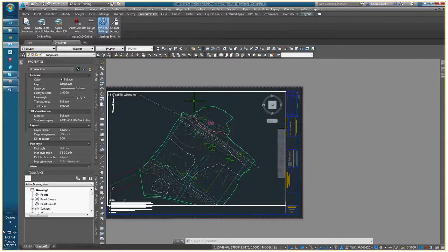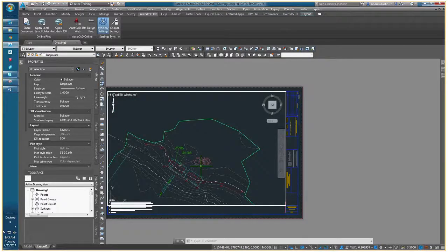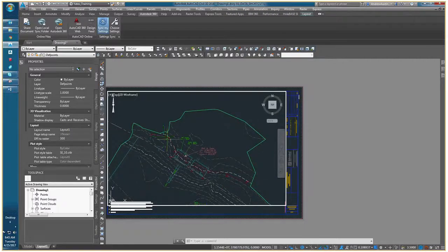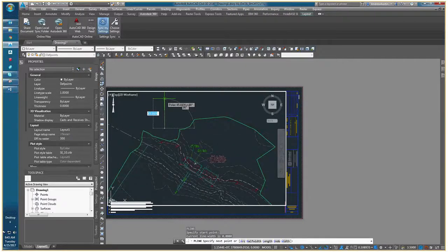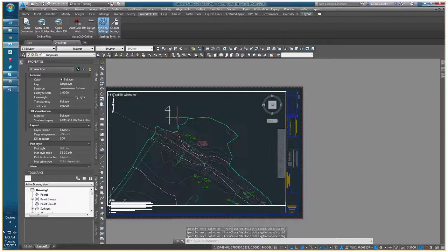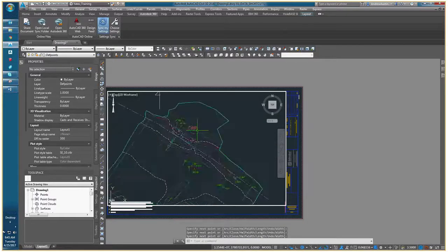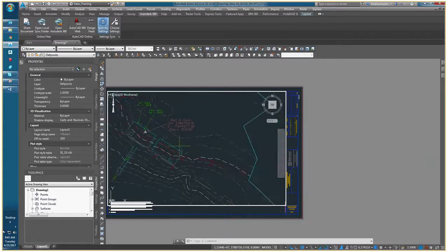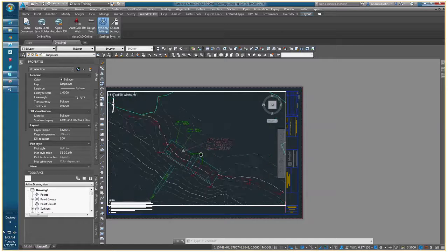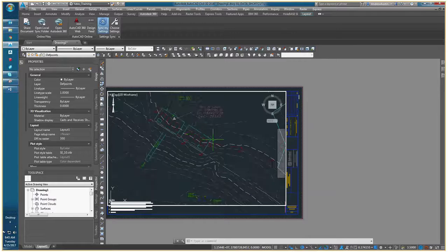So we have the James River up here, and I believe that we're flowing from west to east. So I will likely create a user coordinate system based on that rotation, but I'll further refine that rotation. But if we remember from yesterday, one of the first steps was to create my own little dummy north arrow somewhere in the drawing so that I could keep myself oriented. So the good thing about this is I have actually some reference geometry here to snap to on my UCS command. So I'm going to use this intake line work to develop my user coordinate system.